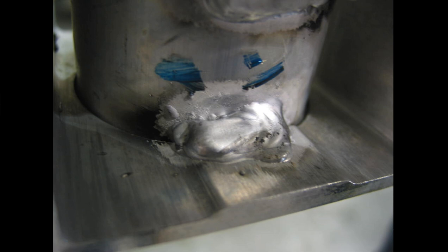Here's a cup weld that was reworked, but nobody paid attention to undercut. This is the undercut that you need to pay attention to, and this undercut has to be filled. And see the way it's rolling here? This particular thing, which happens to be a cup, is a little bit thinner than the base metal, right? Especially when they very nicely gave us a little extra thickness here to try to absorb some heat because the cup's a little thin. But the welder who inspected and decided what needed to get done did not pay any attention to the cup,